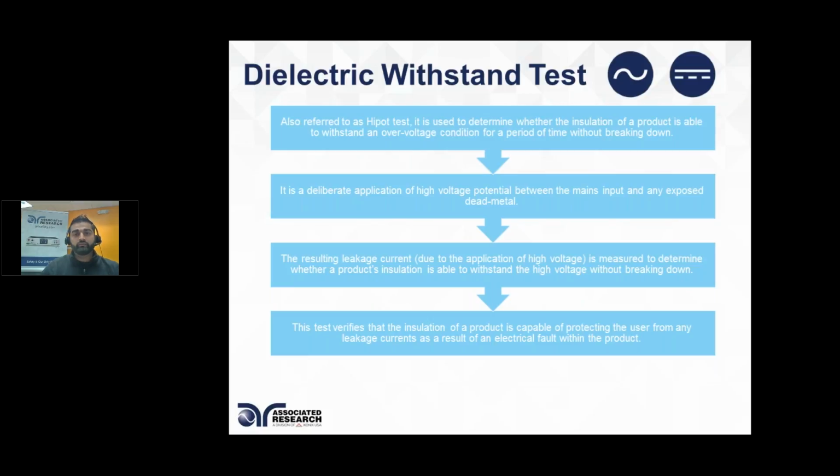And the dielectric withstand test or the HiPot test is ensuring, we're applying high voltage to ensure that this insulation throughout the life cycle of the product, if it was ever exposed to any high voltage, is still able to withstand that voltage and not break down. So we're deliberately applying high voltage, which is applied to line and neutral because they're both line carrying conductors, and then we're stressing the insulation from those line carrying or current carrying conductors to ground. At that point, any insulation that falls in between will be tested for high voltage, or potential of shorting out or potential for arcing over.